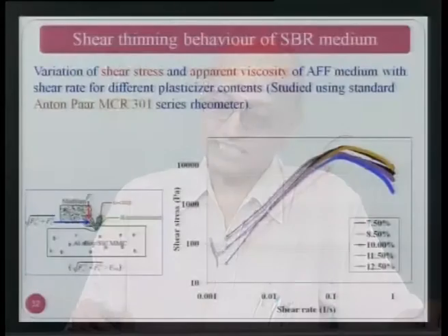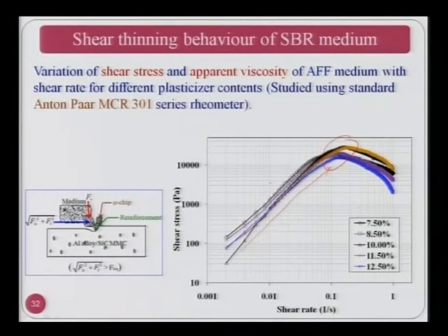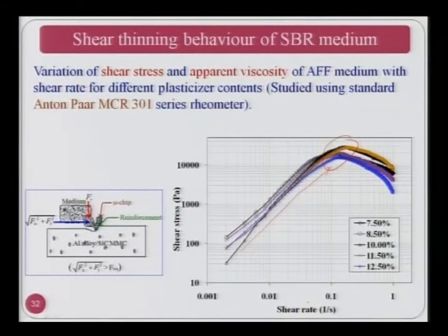But when shear rate increases up to a certain value, shown over here, then the shear stress or shear capability of the medium starts decreasing, and this phenomenon is known as shear thinning. This is really able to explain many of the results which have not been explained so far, as far as the abrasive flow finishing or rotary abrasive flow finishing process is concerned, and from that point of view, this curve is very interesting.